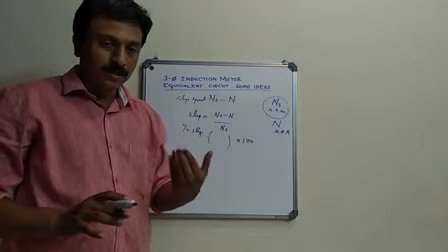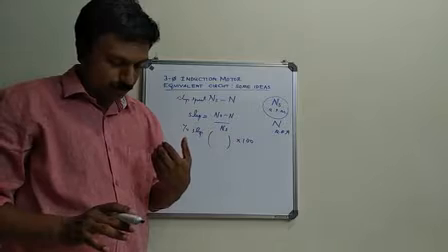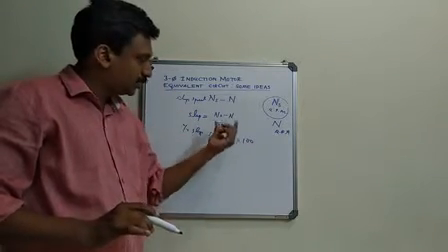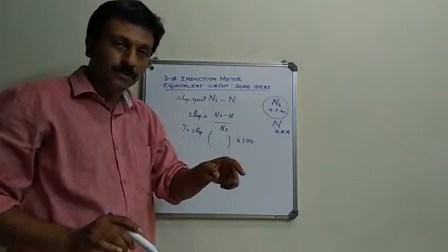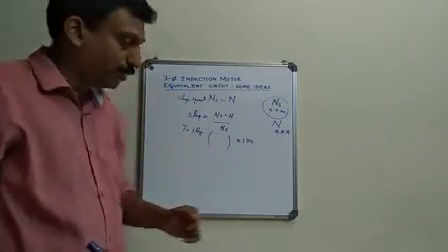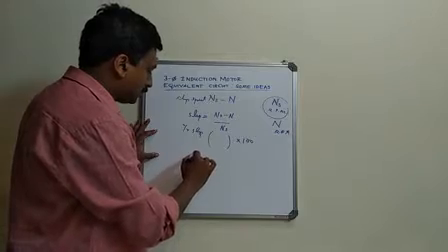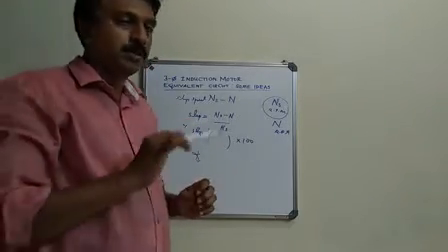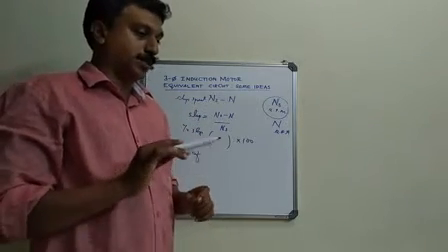When the motor starts to rotate, there is a relative speed, and that affects the frequency of the induced EMF in the rotor. For example, at standstill, the frequency is the same as the supply frequency, because the rotor sees the field rotating at speed ns.